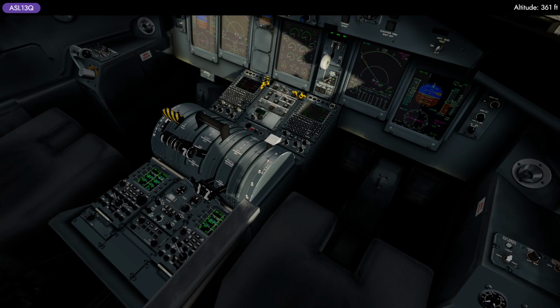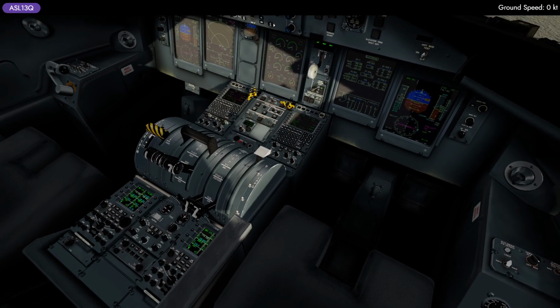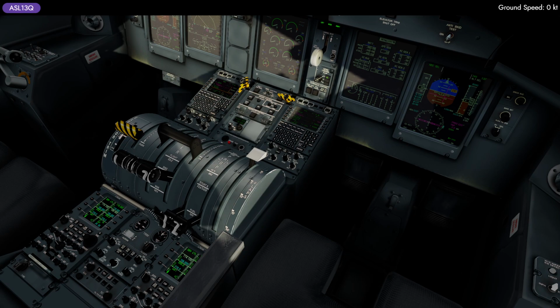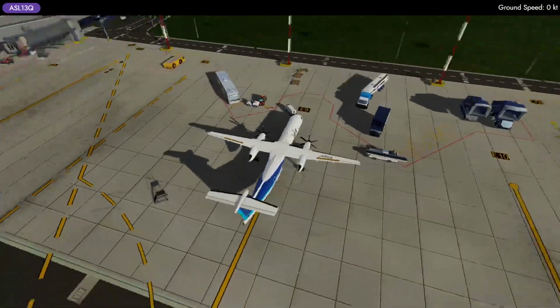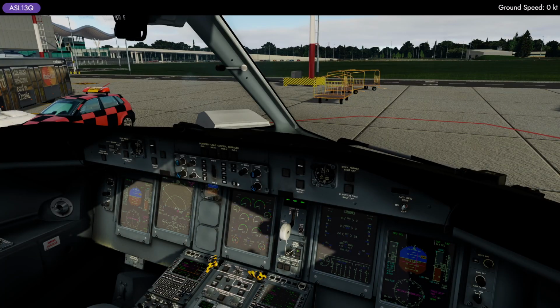Let's select the systems on this page. So the electrical system, now the APU is actually under load. We have disconnected the external, so it's not illuminating anymore. Our engine is okay. Fuel is okay. Check doors once again, all closed, so basically we are good. Let's go back to the engine, and we now should be able to start our engines.